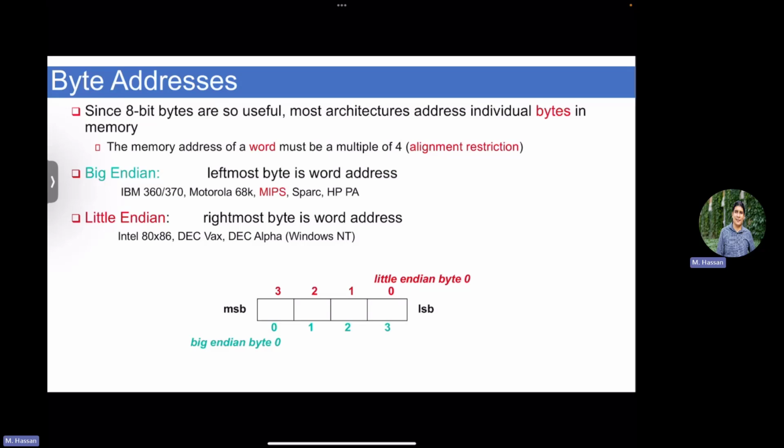Something to understand, and I hope this is already mentioned in 2DI, is that you always assume your memory, this is how every computer is being built, is byte addressable. Did you hear that term before? Byte addressable memory? In 2DX as well, because you dealt with memory in your MCU in the project, right? So memories are byte addressable. What does it mean? It means that any address you have to the memory is pointing to a single byte in the memory.